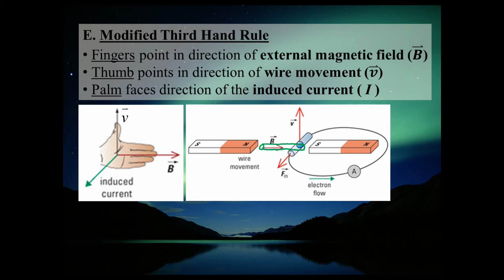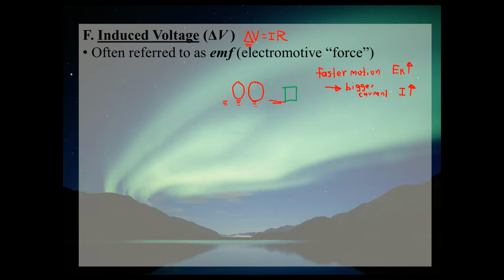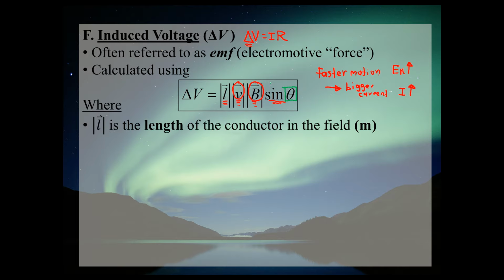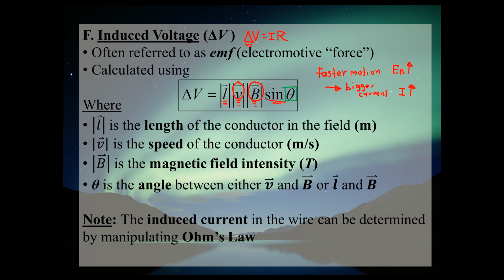In this case, the length of the conductor, L, is also parallel to the magnetic field, and you would induce no current in that conductor. Like I said, I find it more helpful just seeing the equation for induced voltage or current to develop a better understanding of when you can or cannot induce voltage or current in a conductor.